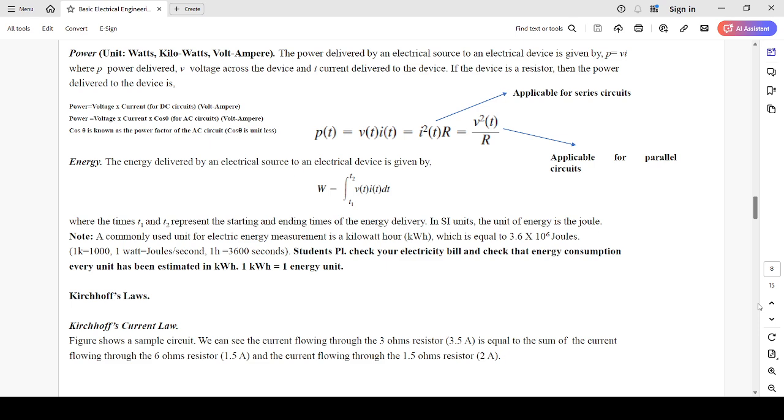The normally maximum value of the power factor is considered to be 1. For a good electrical power circuit, the normal value of the power factor is chosen between 0.88 and 0.92. That is, the value of the power factor is always less than 1. It can't be more than 1. Why? Because it is a ratio of two similar parameters. Since it is a ratio of two similar parameters, cos theta is dimensionless, it has no units.